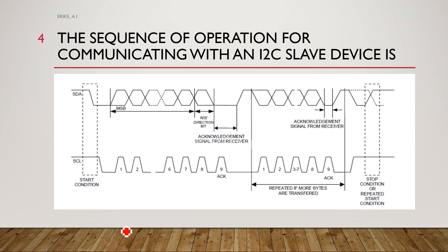So when you look at this diagram now, you will notice that at this particular point, this is logic 1 and that one is logic 1 here, and this place now is logic 0, the same here, this is logic 0. So when it pulls this point to logic 1 and this one to logic 0, that is the serial data; when it pulls this, it is the start condition for data transfer.